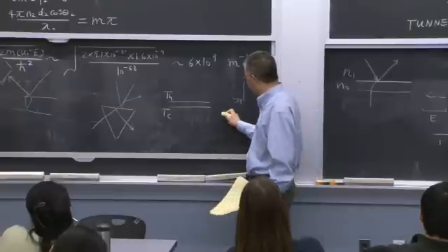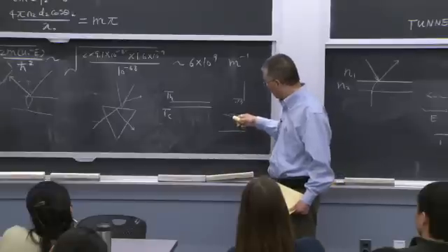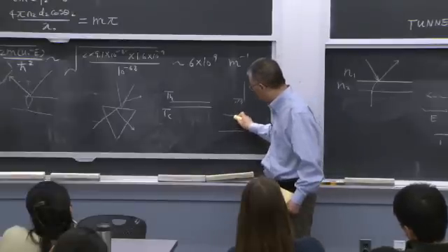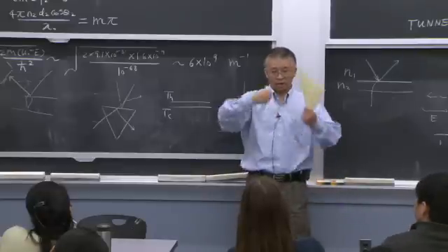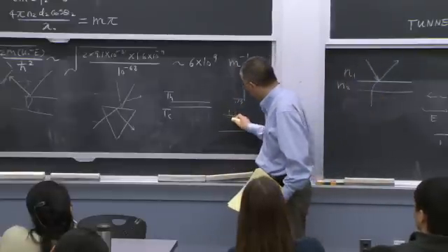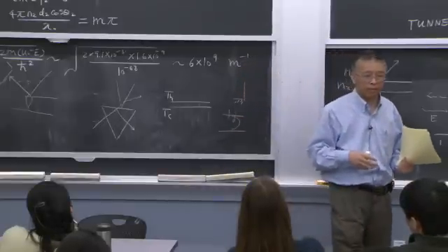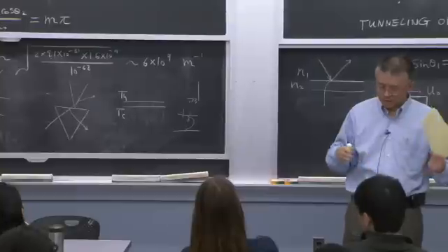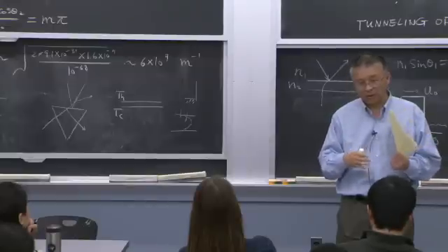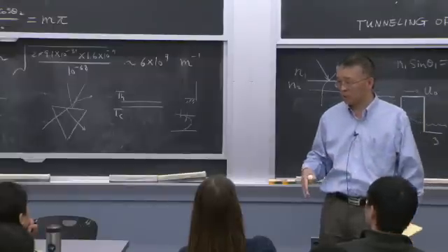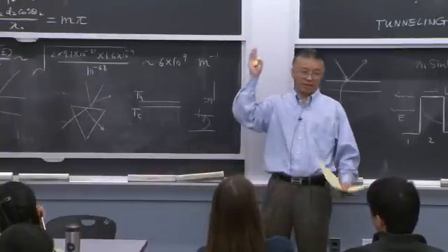So the problem is that when you have two surfaces, say not close by, far apart, when electrons go out, they create a potential, because a charge in the vacuum has a potential. The other electrons now will see that potential. It's hard to get to the other side. So that's a space charge effect. And so their theory, and this Stanford group is also doing, they say, okay, we're doing MEMS fabrication to make it smaller, so as to reduce the space charge effect, which is fine. But then when people say, okay, why don't you do this? So they say, oh, Gang Chen has studied.